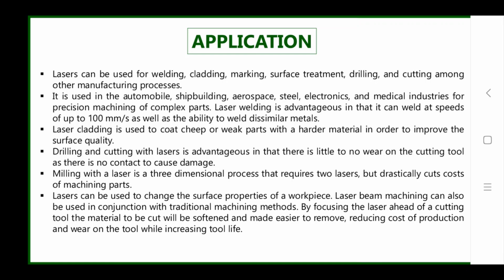Laser cladding is used to coat cheap or weak parts with a harder material in order to improve the surface quality. Drilling and cutting with a laser is advantageous in that there is little to no wear on the cutting tool, as there is no contact to cause damage. Milling with the laser is a three-dimensional process that requires two lasers but drastically cuts the cost of machining a part.